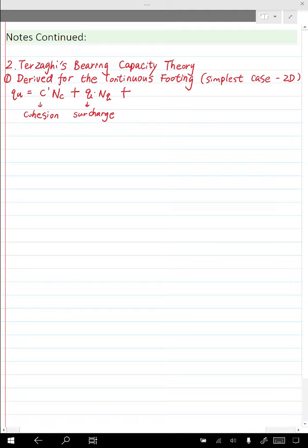If we do that, what we change is the unit weight of the soil, so it's gamma. That's also a proportionality. But traditionally, we add a 0.5 in front of this term because the footing is symmetric. And also, the width of the spread footing matters.